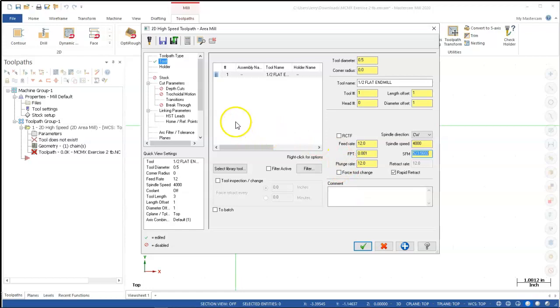All right, so I had not noticed that one, so that must be new for 2020. We only looked at it the last 3 weeks. So tool inspection changed, so apparently it's going to force the macro that goes and sends it over to the Renishaw probe and say, yep, there's a tool there. It's still on diameter, still on length. We have tips: inspect it before you put it away, or inspect it before you use it.